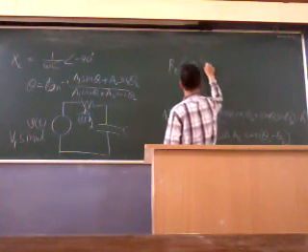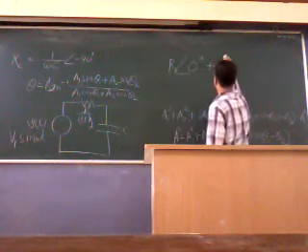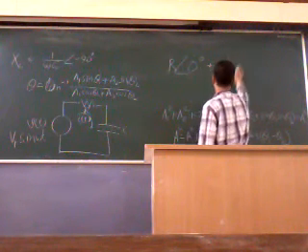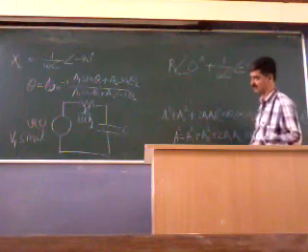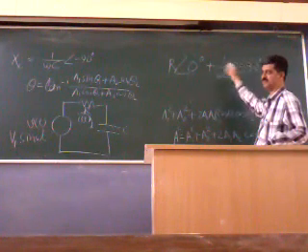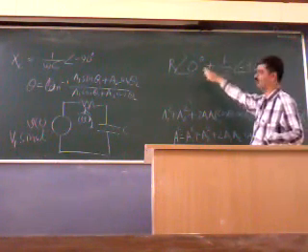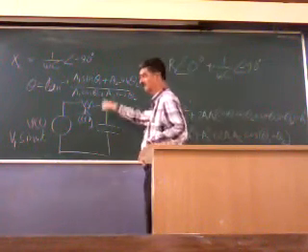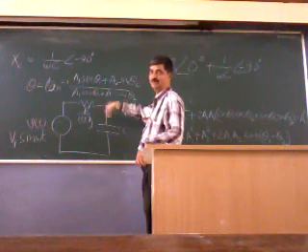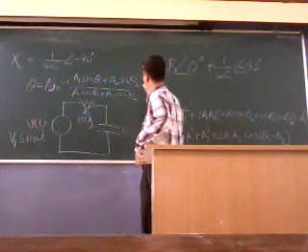R angle 0 degrees plus 1 upon omega C angle minus 90 degrees. The addition becomes simpler because we have 0 on one side and 90 on the other side. So what is the effective impedance? Effective impedance we want to find out. So that would be A angle theta.